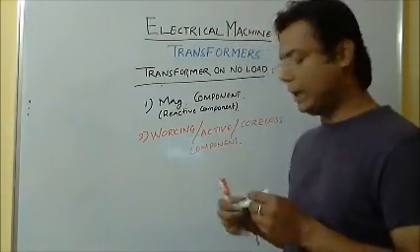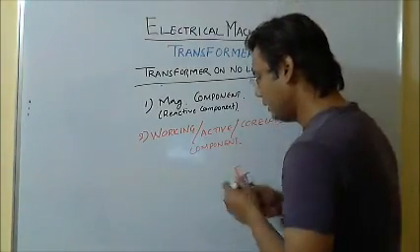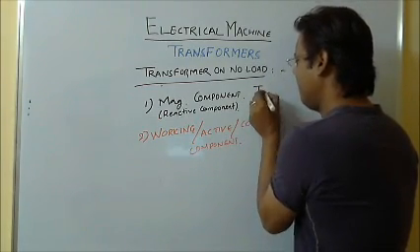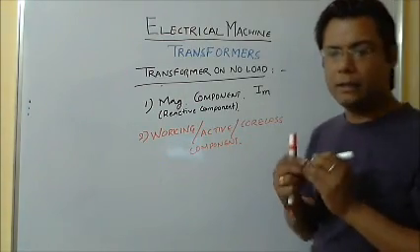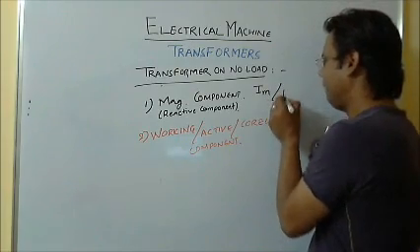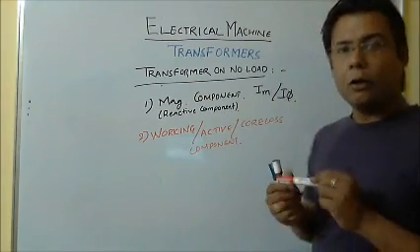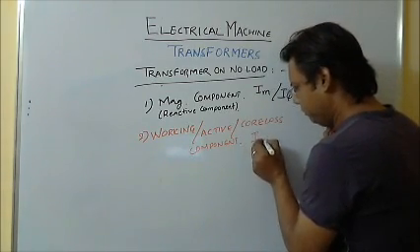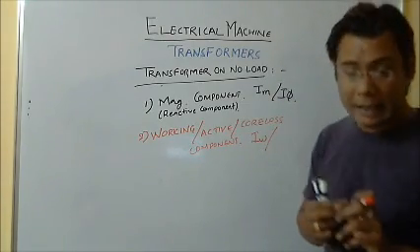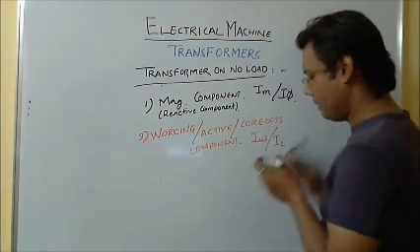So, rather than writing it like this, I can also write it like this. This is called IM, which is called I magnetizing. In some books or references, it is also called I phi. And the working component is also called IW, which is I working, or in some books it is written as IC, which is called the core loss component.